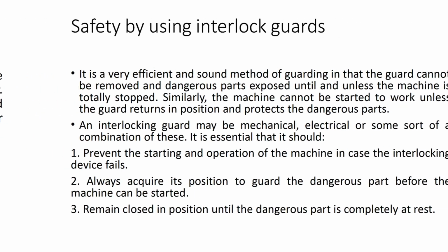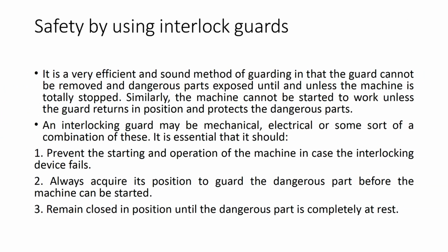Now let's talk about safety by using interlock guards. This is a very efficient and sound method. The guard cannot be removed and dangerous parts exposed unless the machine is totally stopped. Similarly, the machine cannot be started unless the guard is in position. An interlocking guard can be mechanical, electrical, or a combination.